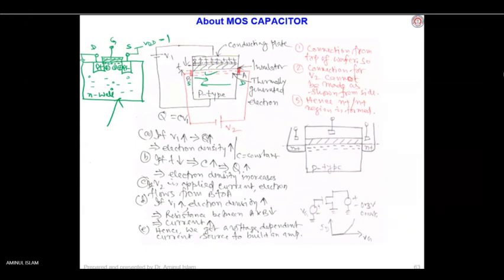In this channel, you have excess holes, which we are calling the inversion layer. Earlier it was inversion layer electrons, the electrons here in the case of N MOSFETs, and it was N plus type. Now it is P plus type. The two regions we have doped with boron possibly, on the N well or N type substrate you can think of.